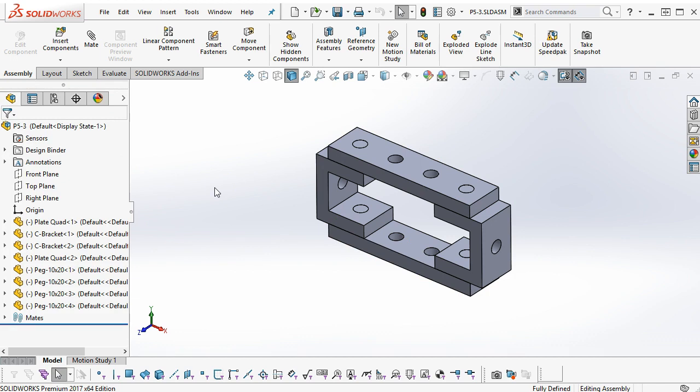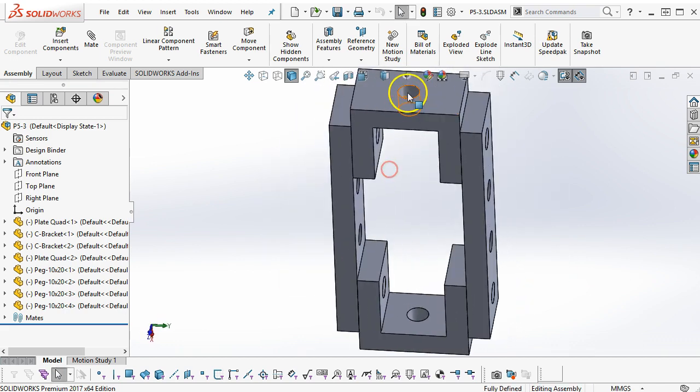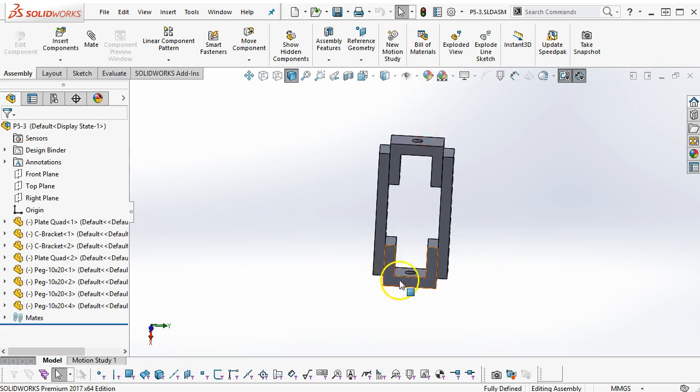Orientation, and we'll do this as a single unit first. If I just wanted to see all of this piece in one print, no clearances, not disassemblable, then I would consider what I'm testing for. And if the loading is in this direction, I would want the layers to run horizontally, across the length of the part. If our loading was through the ends, then I would want to build this way.